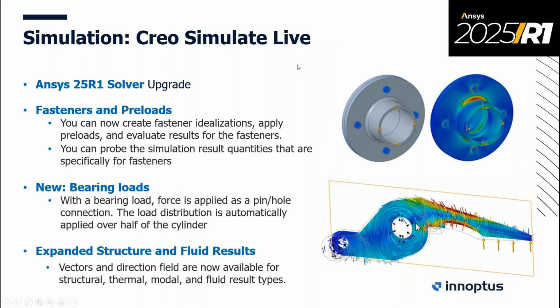Creo Simulation Live. So we have the basic simulation in ANSYS or in Creo, that's your choice. What Simulation Live does is that you can very quickly set up an analysis, and if you have a lot of iterations, you see a direct effect of what you're doing. So for instance, here, if I have that flange and I start changing that thickness, I don't have to do anything. I have to set up my analysis first, of course. And if I then start changing my part and that thickness, I will see, 1 or 2 seconds after I commit my change, the effect on my part.